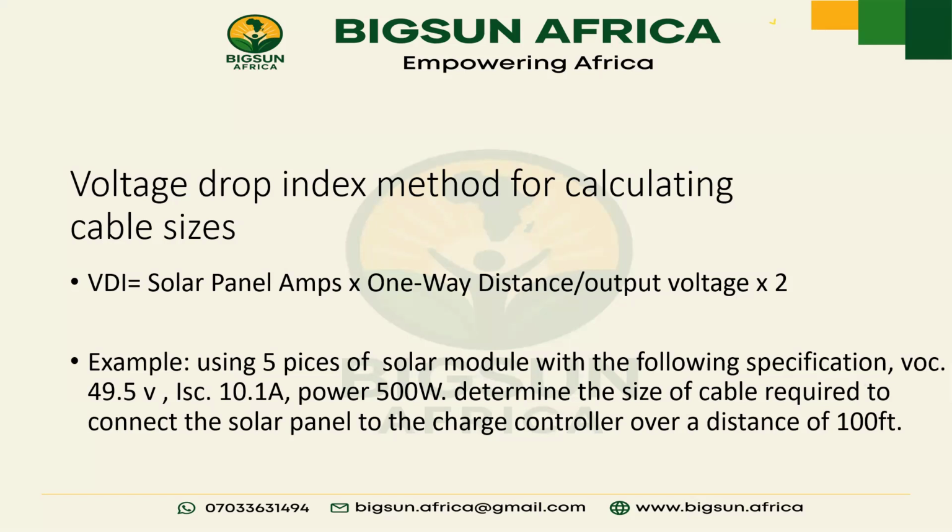Yes, sir. Okay. So then times one-way distance, then over what? Output voltage times 2. Output voltage is the overall voltage of the panel. When you connect your panels in series, the overall voltage is going to be higher than when you connect your panels in parallel. We all understand that, right? Okay. When I say we all understand it, I expect people to say something so I'll know you are with us, not just one person.